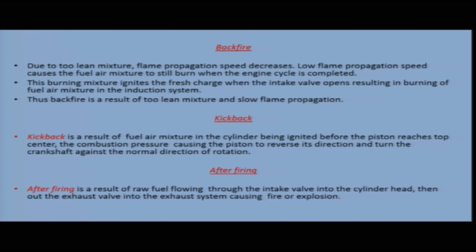This burning fuel air mixture will ignite the fresh air charge when the intake valve opens, resulting in burning of fuel air mixture in the induction system. So, your fresh fuel air charge can burn in the induction system because of the continued burning, because of the low flame propagation speed. This causes a backfire in the induction system and it is due to a too lean mixture and slow flame propagation.